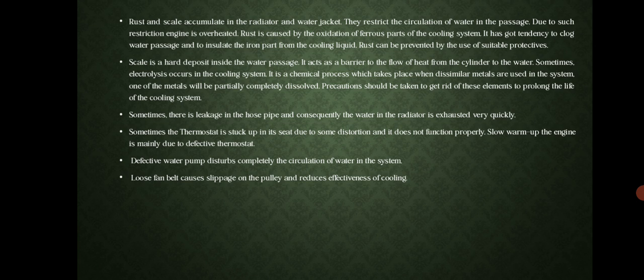Scale is a hard deposit inside the water passage. It acts as a barrier to the flow of heat from the cylinder to the water. Sometimes electrolysis occurs in the cooling system. It is a chemical process which takes place when dissimilar metals are used in the system. One of the metals will be partially or completely dissolved. Precaution should be taken to get rid of these elements to prolong the life of the cooling system.